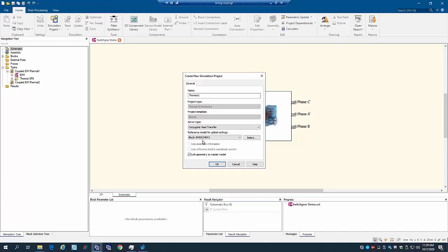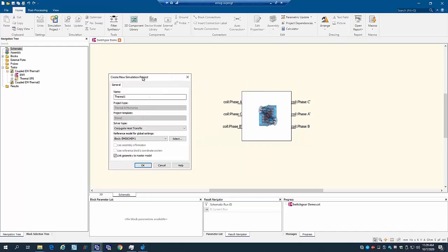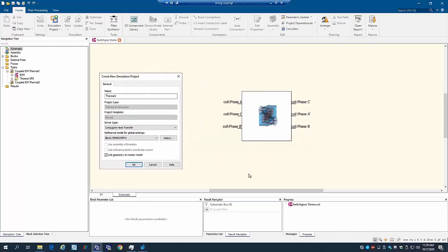The first 2 solvers are still very, very useful. They are conduction-based solver. In other words, they solve accurately what's happening inside the solid. At the fluid and solid interface, at the surface, you need to make some assumptions of the heat transfer coefficient. Remember, we have a calculator for that. But usually, the surface are not that simple. There's no flat surface in the switchgear, for example. It's really hard to estimate what that is.